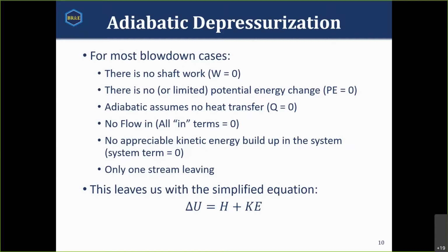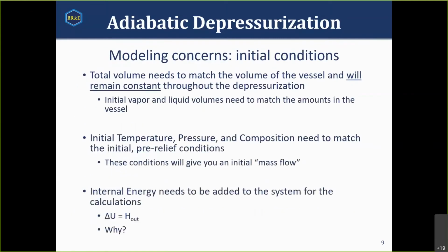Therefore, I can throw out the other in stream altogether, which all said and done, leaves us with one simplified equation. My change in internal energy, I'm pointing to my screen, you can't see it, let me use the mouse. The change in my internal energy is going to be equal to my enthalpy plus kinetic energy. Now, for those of you who were paying attention, you'll notice that I'd said initially my internal energy is equal to my enthalpy.